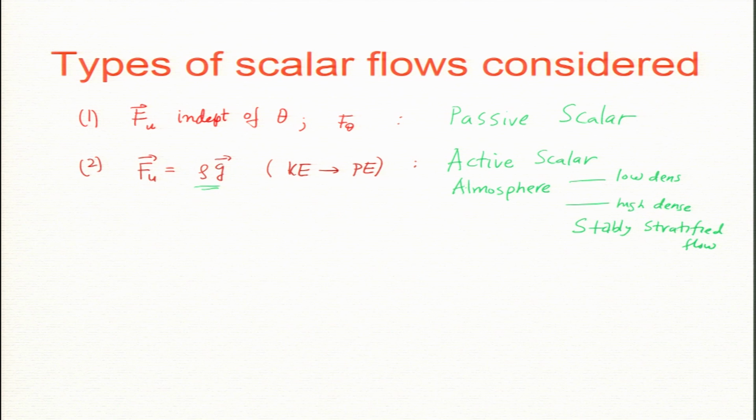So, the third case is, in fact, the same force rho g, but we write it in terms of temperature. Density is inversely proportional to temperature: the hotter the fluid, the lower the density. So, this is minus theta, the temperature fluctuation.